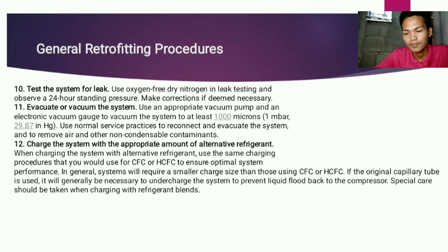Number 12. Charge the system with an appropriate amount of alternative refrigerant. When charging the system with alternative refrigerant, use the same charging procedures that you would use for CFC or HCFC to ensure optimal system performance.